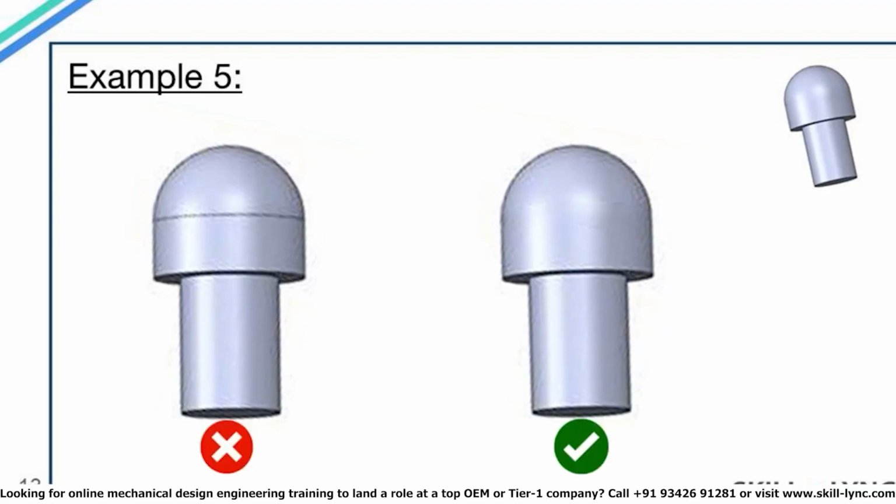So in this case, the parting surface on the right side will be preferred just because there won't be a visible parting line in the final model. The selection of the parting surface between these two cases is made purely on aesthetic basis.